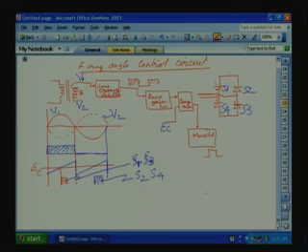Let us take a ramp generator using an operational amplifier. Many ramp generation circuits are available in the book. So, you have this one. There is some 22K you can put, and a 10K pot you can connect to minus 15 volt. So, give it here, and there is a capacitor here.